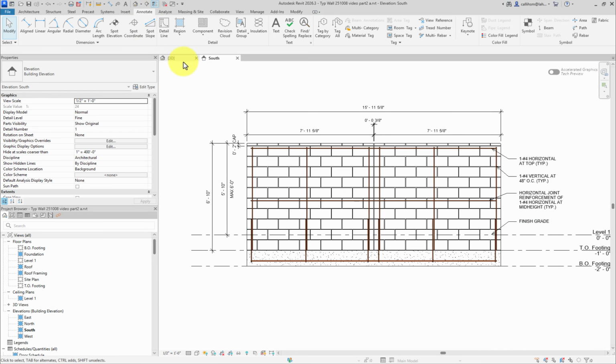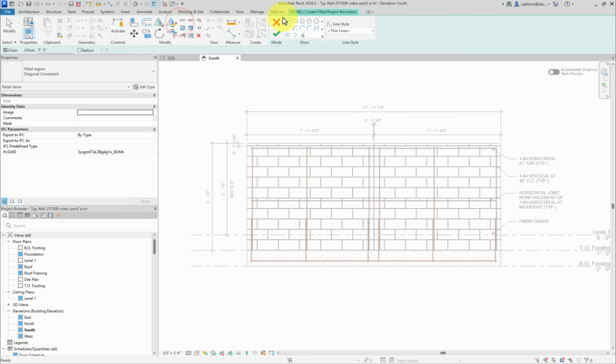So annotate, and of course in Revit hatches are called regions. So I will go for the green pick line tool here because that's giving me the ability to pick up a lot of these edges, and I'll use it as much as I can, and then maybe fillet there to there, and then I can pick line on this again, and then fillet there to there.